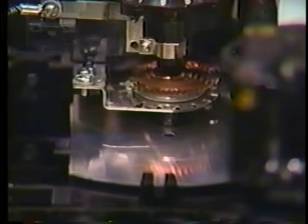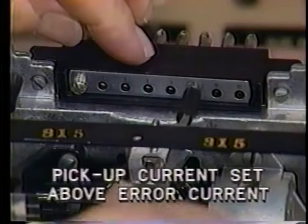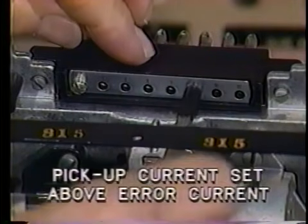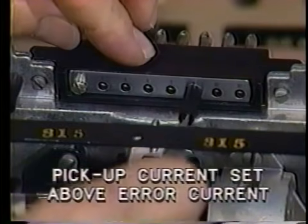But this may have to be increased if the bus is located close to a generator. The pickup current should be set so that it's above the estimated error current generated by the CTs for the through fault. This system is quite economical and is often used on low voltage buses. But you can see that it's slow and not very precise. More sophisticated arrangements are needed for protection of high voltage buses.